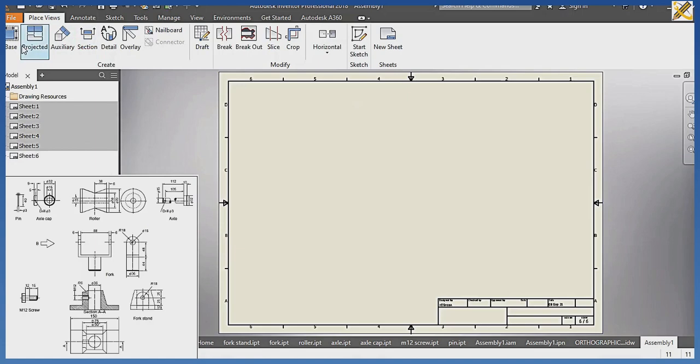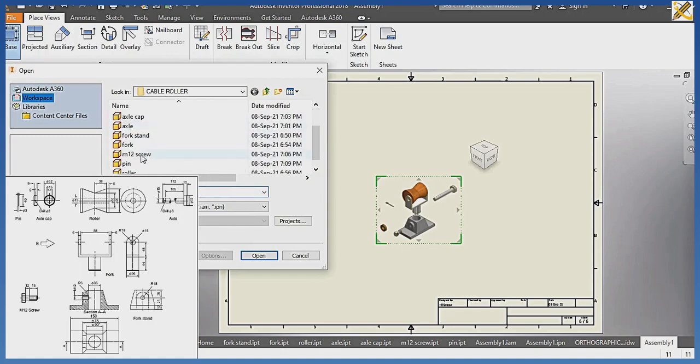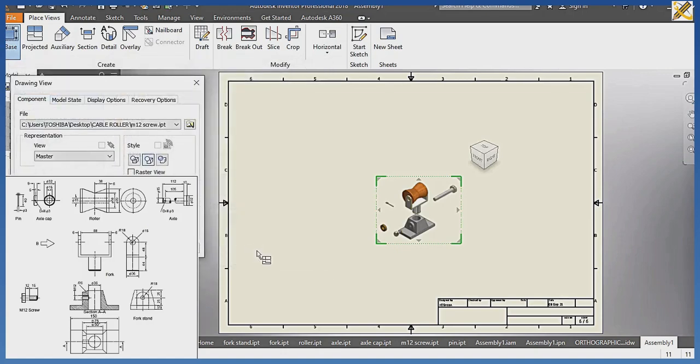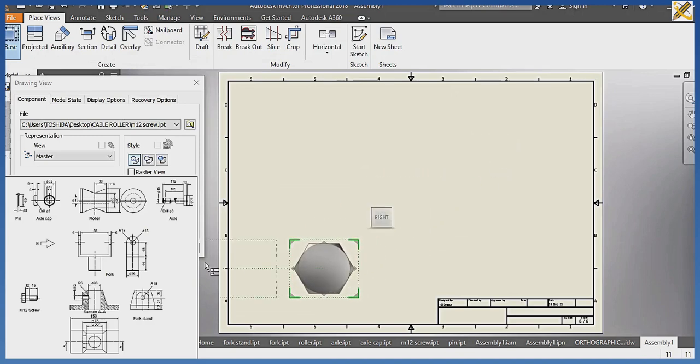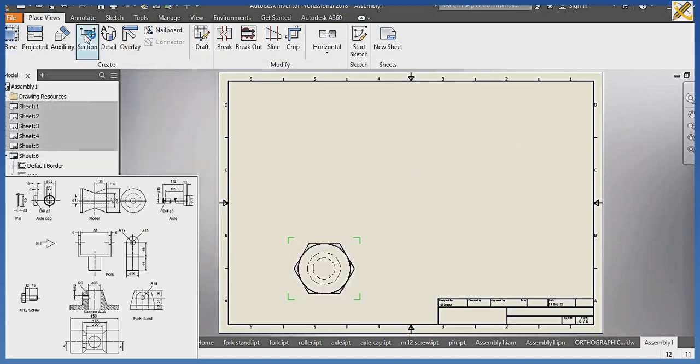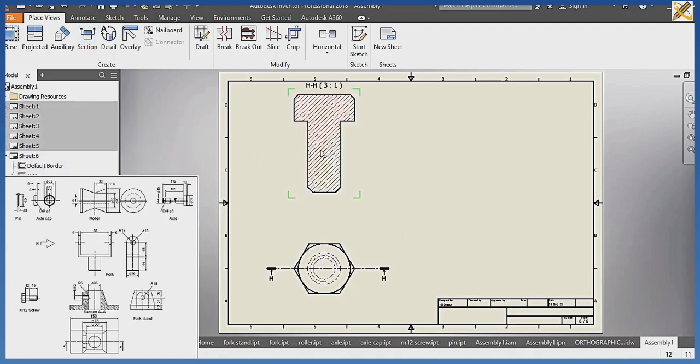Coming right here, new sheet, base. Okay, so with my base, clicking on balloon. On my balloon, I'm having M12 screw open. Okay, with open, showing the plan right there, coming down here, clicking my okay, clicking my section, clicking this box, coming right here, facing the top. Then continue, and okay. All right, so clicking right here and clicking right here and hide.